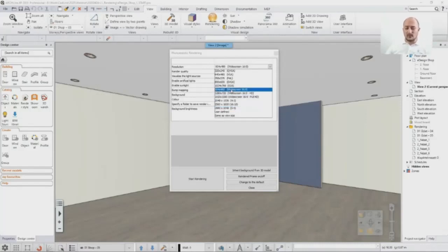So for yourself, you will always render images in lower resolution to have a much faster render, but for your clients you will go with either this or this, something larger, because they will likely see your images not only on their mobile phones but also on large screen TVs in their home. So to avoid having blurry, not good quality images in terms of resolution, you should render larger resolutions for them.